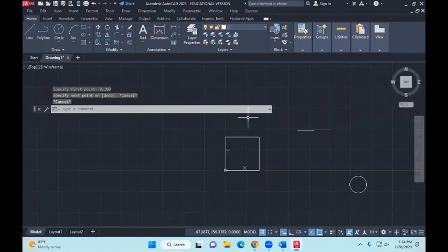Okay, so what I'd like you to do is go to dynamic input, make sure, if it's in blue, those buttons at the bottom, if it's in blue, it means it's turned on. You turn off dynamic input so that all of us are on the same page, in the sense that everything we type will be in the command area. Not some things typed in the crosshair place and some things typed in the command place. So everything will be in the command area and you can click and type numbers or words, whatever. So just turn off dynamic input. Got it? So that should solve the problem that you're not able to type 0,100 or 100,100.